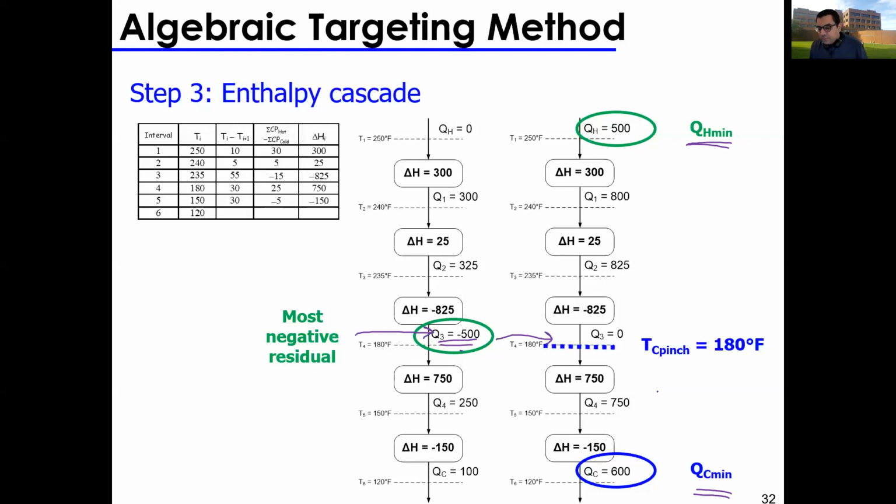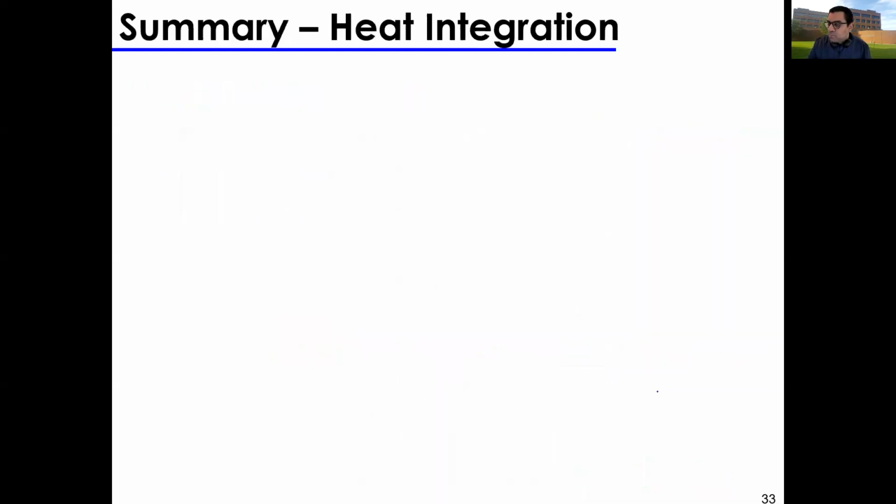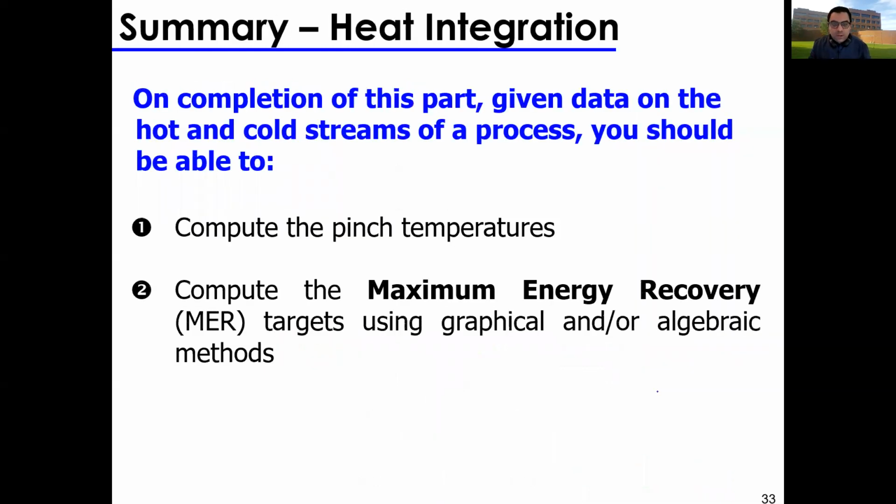Okay, so this is the end of this lecture. It's a bit of a long lecture, but this is a very important milestone in this course. You should be able to compute pinch temperatures using the two approaches. You should be able to build your composite diagram, and you should be able to compute your maximum energy recovery targets using both graphical and algebraic methods.